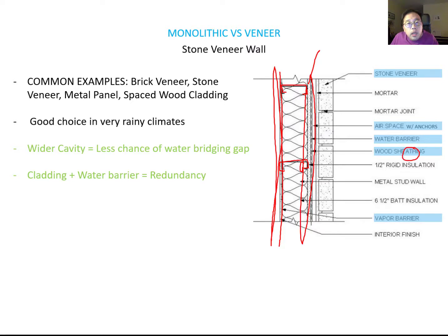You remember, to cover this sheeting, you need to add the waterproofing membrane over it. And you remember that to make a better-performing wall system, you need to add rigid exterior insulation over the waterproofing membrane. And then over the waterproofing membrane, we provide cavity space.